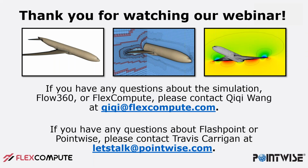Okay. And another question for you. Many solvers prefer extruded meshes near surfaces, like we generate with Pointwise with our T-Rex algorithm, for accurate analysis. Is Flow 360 accurate on fully TET meshes? Yes, we are fully accurate on TET meshes. Although right now we don't have a wall model, so we need the Y plus to be around or less than 1. With that, even if you have a fully TET mesh, we are accurate. Okay.